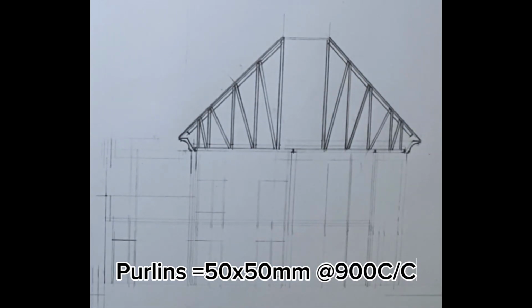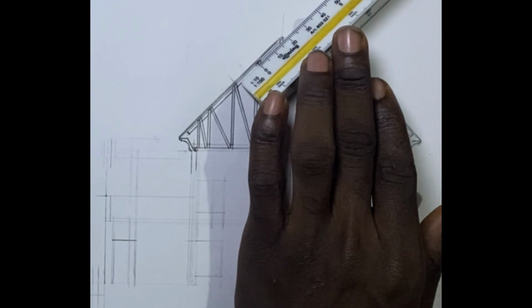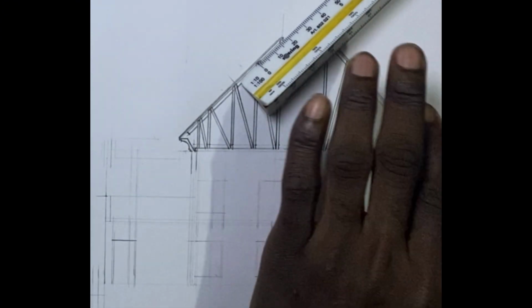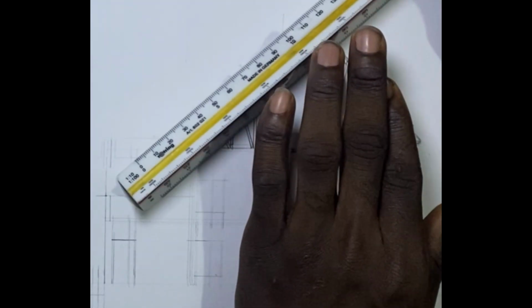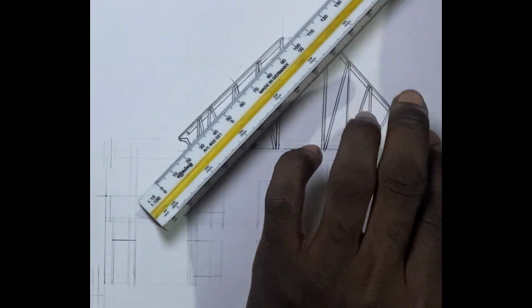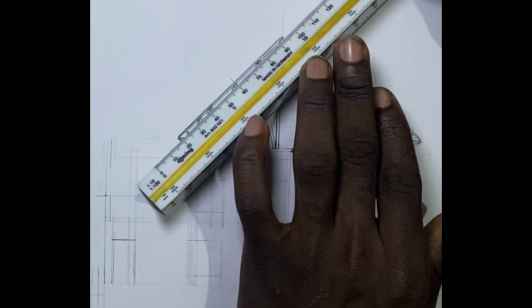Right, and for us to ensure that we all know that purlins are in most cases and generally at 900 center to center. Our purlin is in most cases 50 by 50 millimeter, placed just right on a rafter, nailed to it at the top. So we decide to have our purlin starting somewhere here, just very close up here.